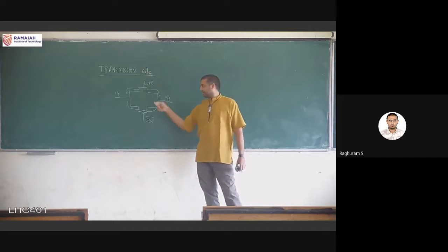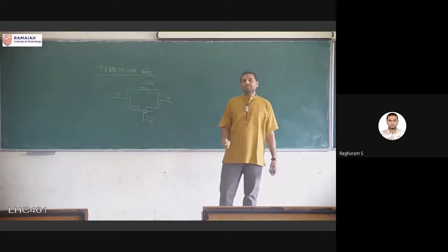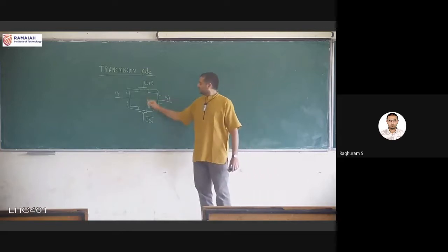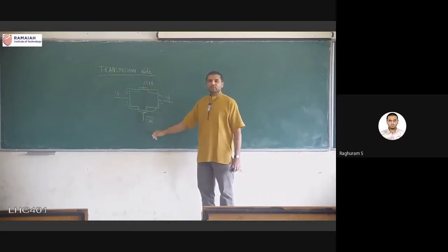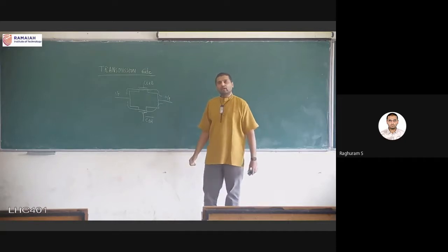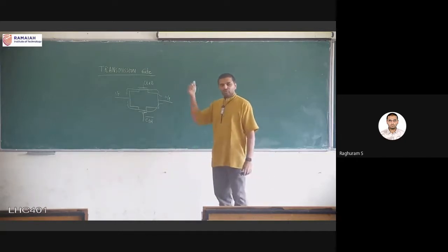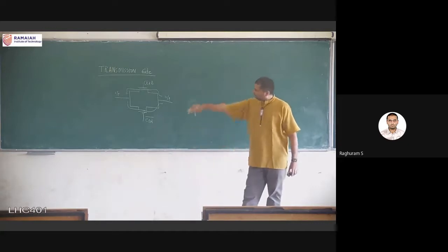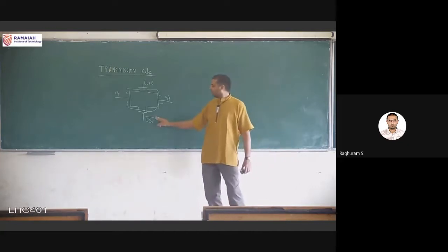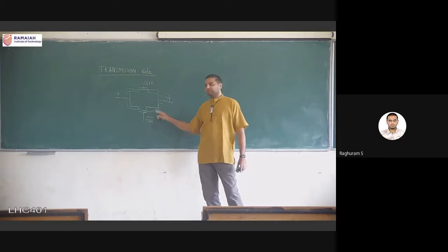First thing. Second thing is, please remember the control signals. Suppose you give the same signals to both NMOS and PMOS, then what will happen? I have control given to NMOS transistor. I am giving the same signal. Here I am having a complement. But without the complement, if I give it to the PMOS transistor also, there will be a problem.